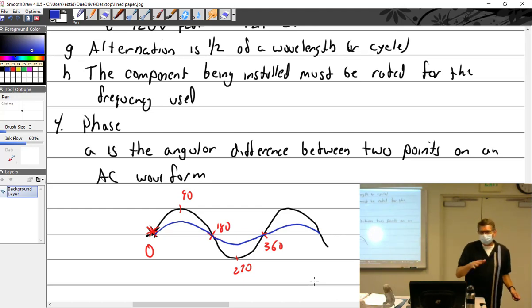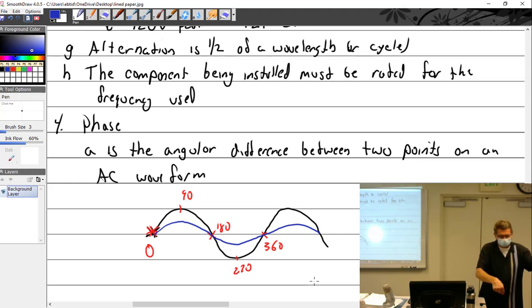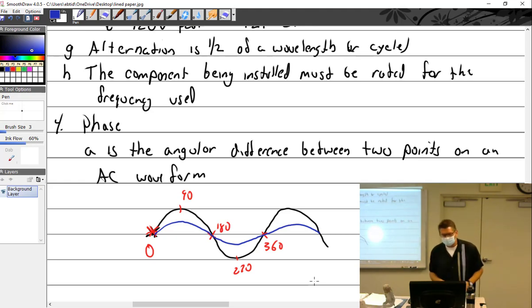You break apart, well, you don't always have to. Now, a lot of you, what you may want to try is try it a couple of times. Try it to measure amperage. I recommend you put it in parallel across something, watch the meter go to crap, then swap the two leads, watch it go to crap, then take them off, then break the circuit, then put it on, and then watch it, and then switch them one more time. Best method out there.